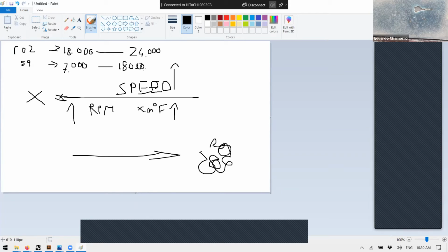When things become fast, everything becomes way more sensitive, and at the same time, you cannot make mistakes because this number ranges way faster. So how do we solve this? By reducing the number of flutes to the lowest possible. That means here, for example, we always try to use one flute, 2 flutes at a maximum. That is already good because 1 or 2 flute end mills are really forgiving. They have a really wide range of working space.